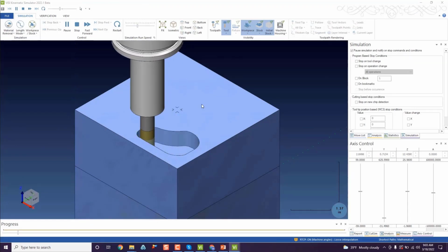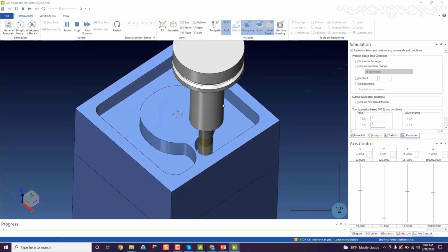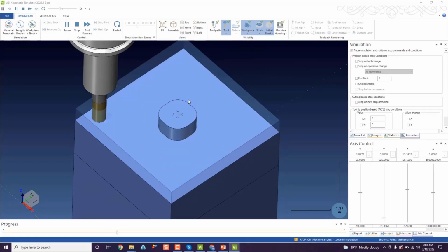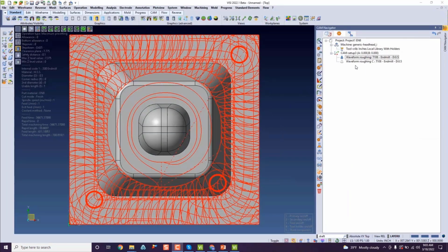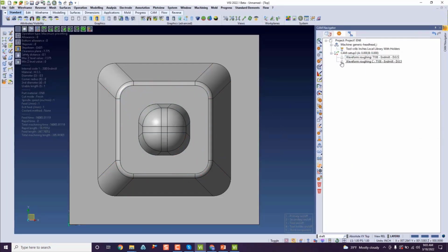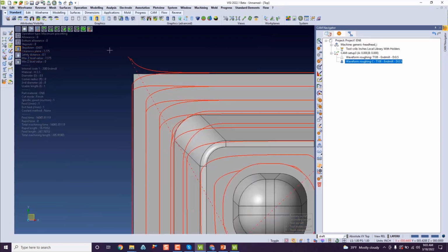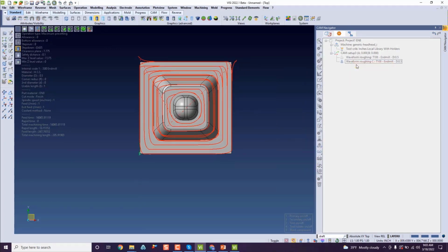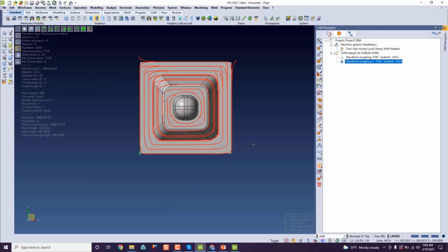Now when you're working with harder material, this can cause issues with tip breakage, more pressure on the tool when it's working in a downward fashion into the part, meaning that the chance of your chips actually welding into the flutes of your tool is higher. Just a lot more issues can happen when you're trying to plunge into a part like that. But with this expand value checked, we now have the option to actually have our tool approach from the outside of the part and be able to work in an outward-in fashion.